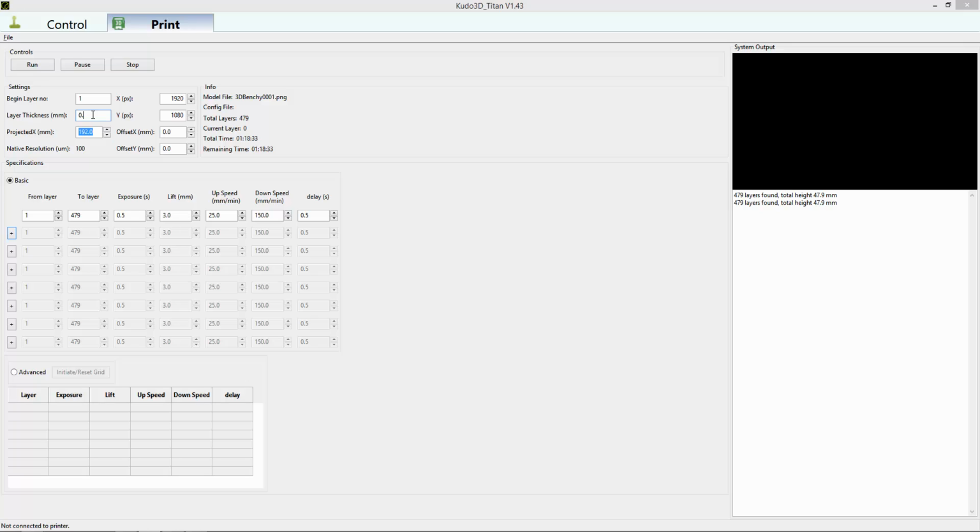If you make a mistake, like set this to 0.5, bad things may happen to your print, especially since then the shrinkage will be significant on the attachment layers. The biggest we want to go generally is, if you're doing a draft, you might be able to go down to 250 microns. But generally speaking, I usually print at 100 microns, 0.1 millimeters or less.